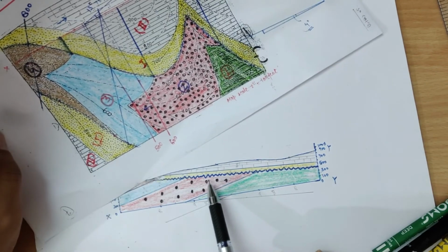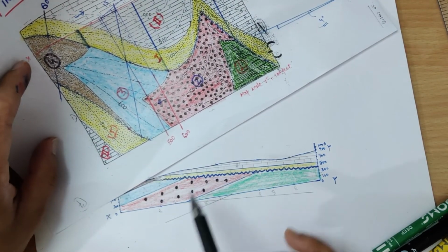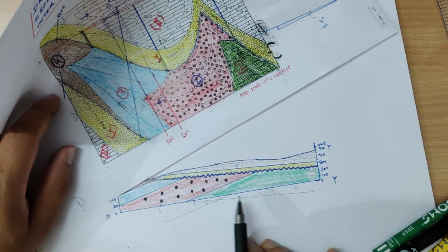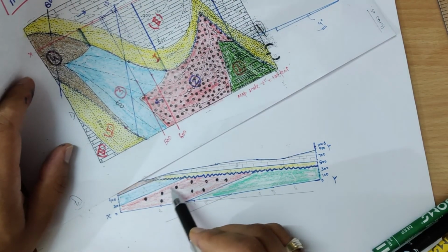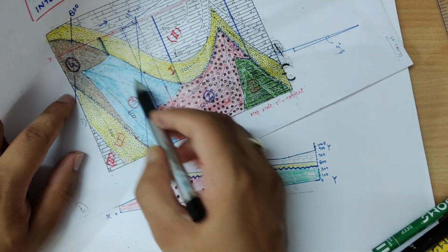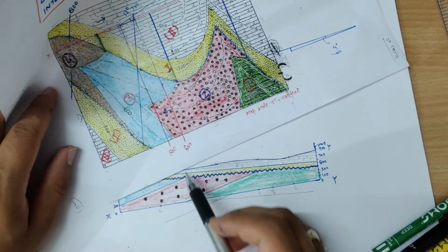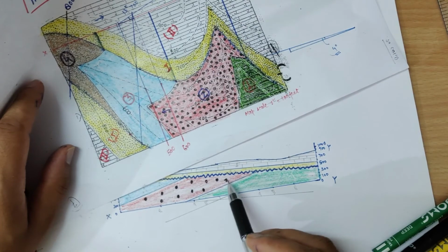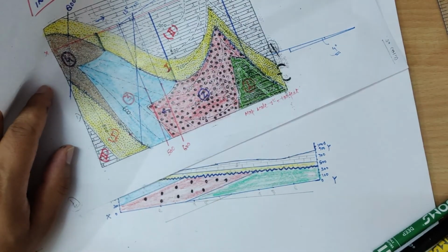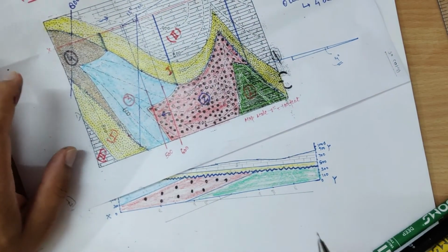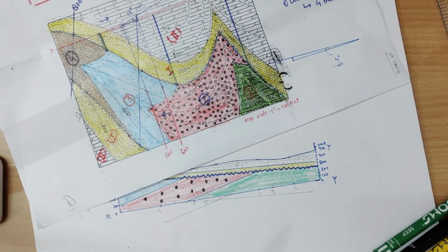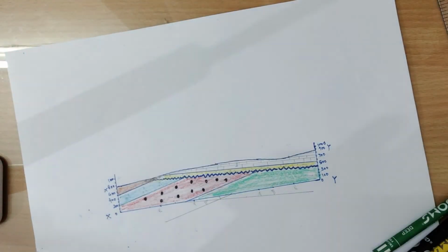So for that you need the cross section of this particular area so that you drill at the exact point and get the same beds. Let's say this is the ore deposit bed. So how are you going to get it? By exposure only, because this will not give any idea of how the beds are going deeper into the ground. So you need to dig out only this portion. So in order to do that you need cross sections. So you prepare the cross section with the help of structural data and surface data.